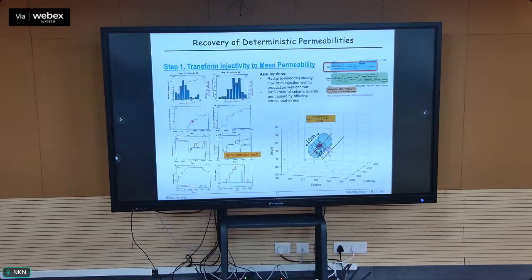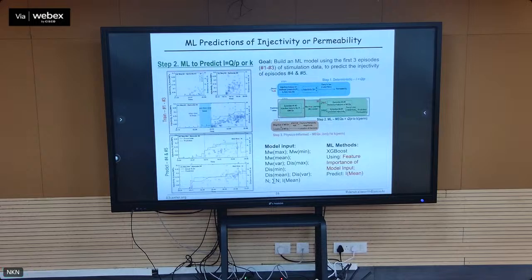And if we know the magnitude of how that contour, the radius of this evolving pressurized zone evolves over time, we can try and fit that to the data to be able to use that to calculate the magnitude of permeability, since we need a characteristic length over which pressure drop occurs with a given flow rate to define the permeability of the system. So that gives us an ability to evaluate in a deterministic way the evolution of permeability within the system. So with those magnitudes of permeability, we can do 2 things.